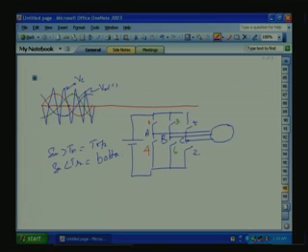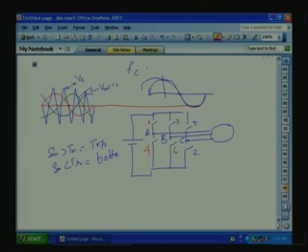Now, how to choose the triangle waveform? For motor drive applications, we want the PWM waveform to have the same symmetry as the sine wave. We should have quarter wave symmetry. When you fold it, it should exactly match, and the negative half should be equal to the positive half. So, we will always use FC as an odd multiple of FM, our modulating waveform.